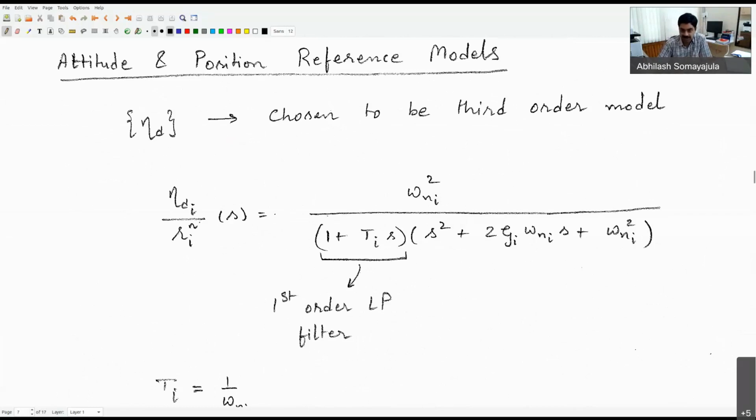I may also want to have a guidance system which can directly guide my position tracking rather than just the velocity tracking. So the previous one which we looked at is only giving me the desired velocities. It doesn't tell me anything about the desired position. I have to integrate those velocities in order to get the position. Correct?